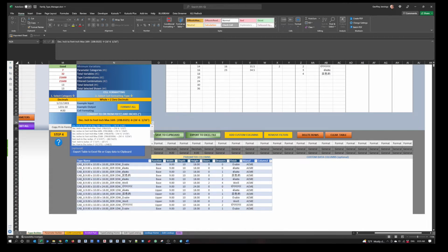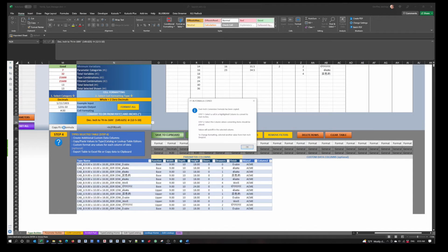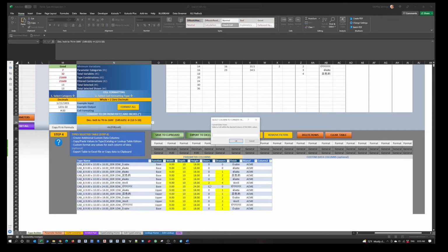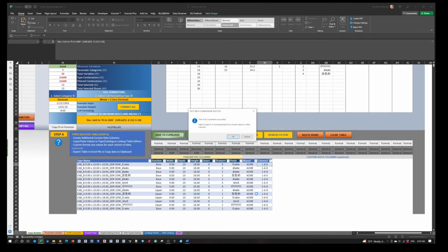So you have options to pick which type of measurement you want, from inches to feet and feet to inches. So let's just say we're gonna grab this one and I'll copy it. It's gonna say okay, that's when it's selected. Here's what you can pick from. We're gonna grab this one, click okay. Where do you want it? We picked height, that's correct. And I'm gonna place it right here. And now everything's gonna automatically populate in feet and inches.